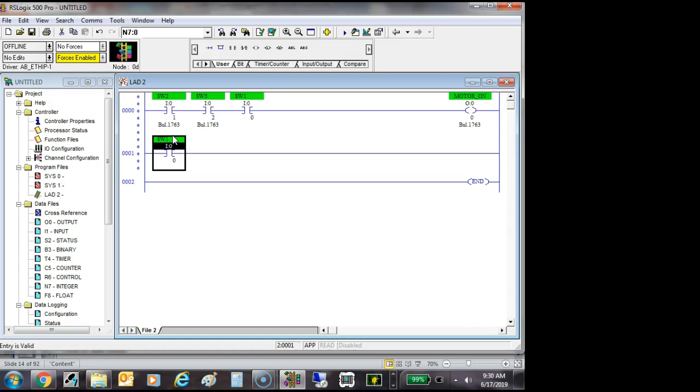A lot of times we want to use the same push button in multiple rungs. It's real hard to do in motor controls, because your switches only have so many contacts. You can't have 100 contacts on a manually operated switch. The PLCs don't care. And ladder logic don't care.